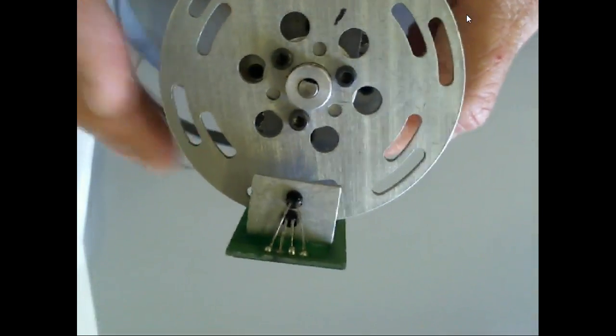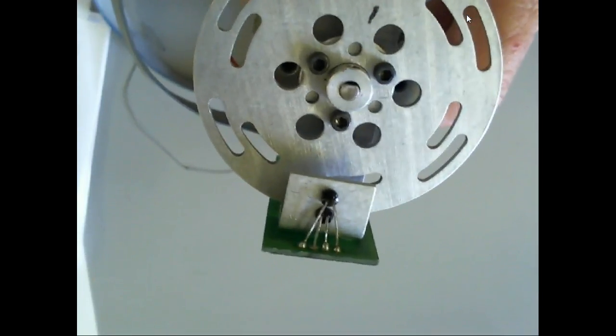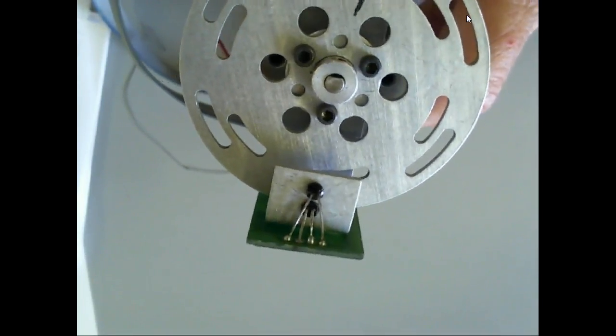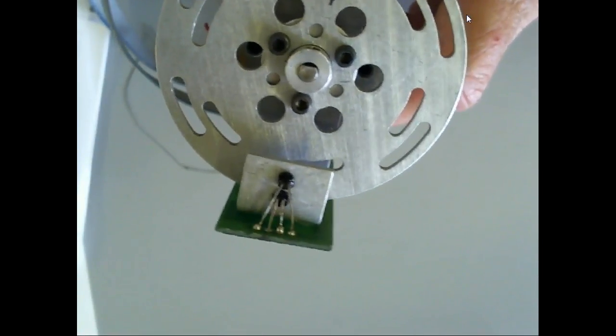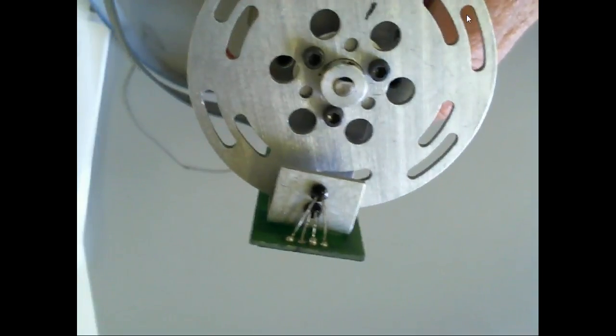So what we did on this robot is we had a little program called the Zero program, and they had limit switches mounted on the robot, and we would run it until it hit those limit switches, and when it hit those limit switches, we'd zero our count out. And that's the way we had to do it, and it was all done by software. So these were our first servo motors, or encoders, that I actually ran into.